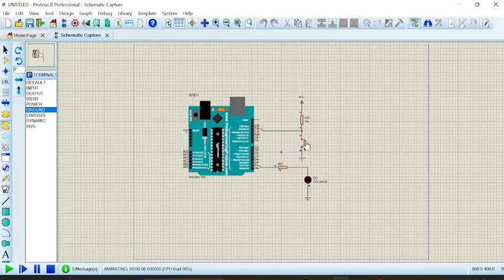This is due to the fact that as pin 12 is becoming low, the LED turns on. But when you release your hand on the push button, it goes back off because pin 12 turns back to the high state. So this requires your hand to constantly be on the push button for it to be on. Or when you release, it goes off.